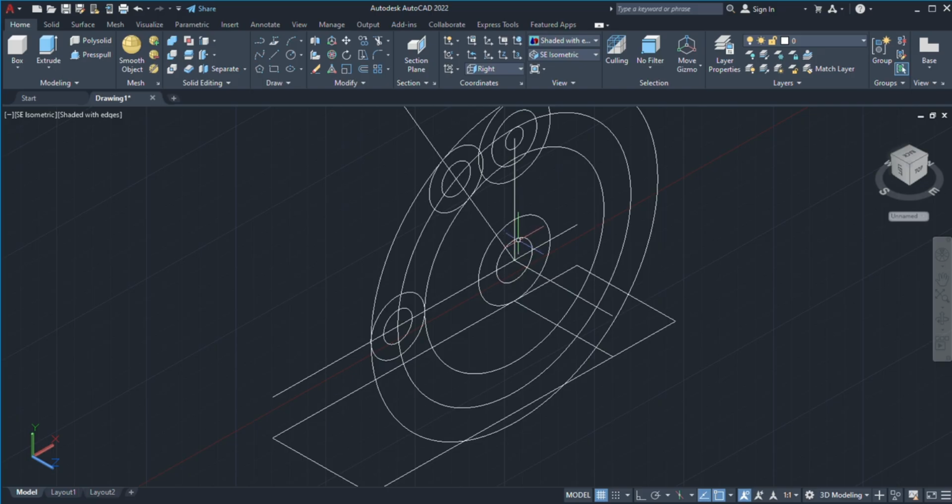Having those, I think we only have one thing left, a line with a 15 degrees inclination. We have not been told the length, so we just take the line command. The starting point is this corner.